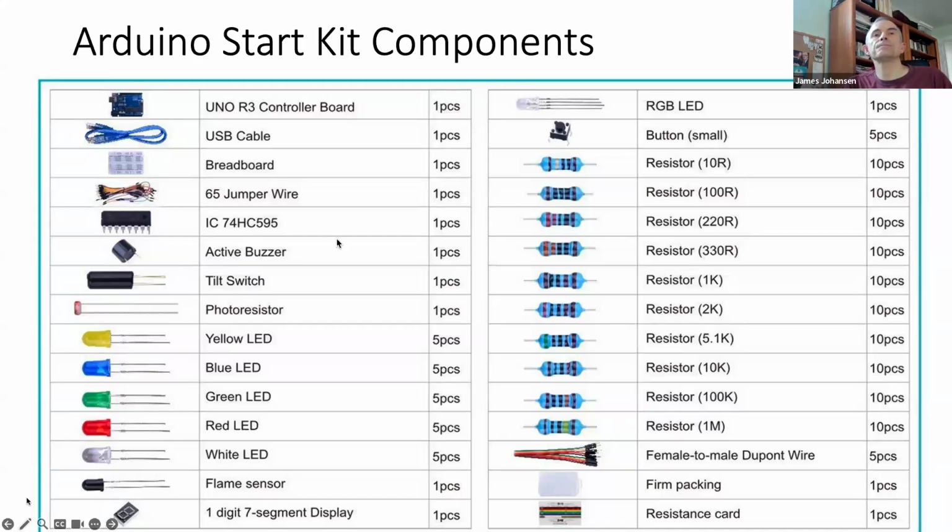And so this is a blow up. You should have something like this, a piece of paper in your kit that will be describing the various elements. And here is something fun. I can show you, I won't show it today, a photoresistor. When light hits it, it reports out a value that you can read in from the Arduino in a console on your computer, and you can either get a number or you can have a graph. There are different ways you can see that. So that's something interesting that we can leverage as a sensor. This is a light sensor.